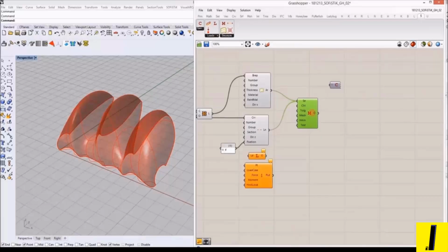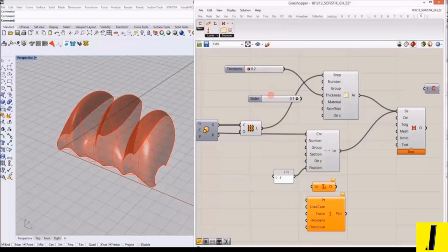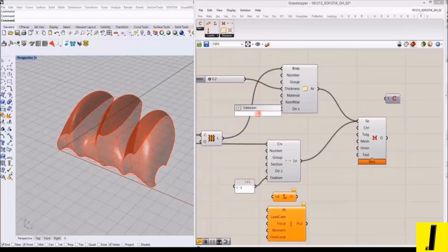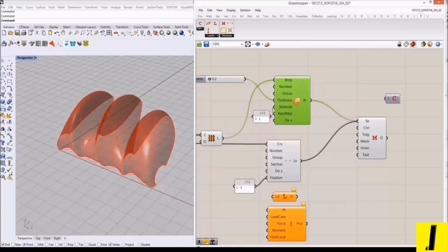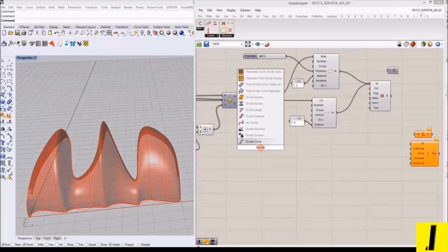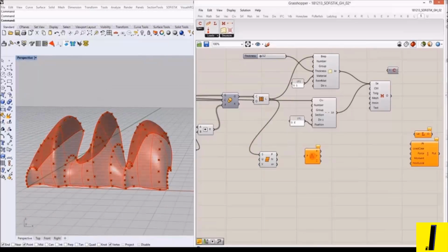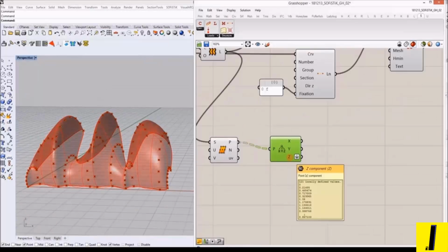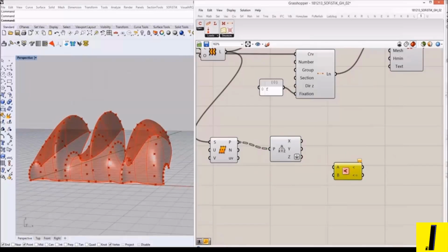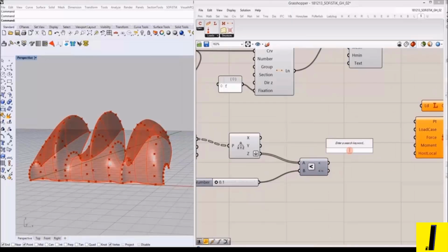And as you can see, the Grasshopper geometry surface can be converted to a structural area, and we can define the thickness, and also we can give a group name or member number, and we can also define the support and the member definition out of Grasshopper. And here Grasshopper is really flexible. In real time we can manipulate geometry, and we can define different parameters. It's a so-called parametric design tool.